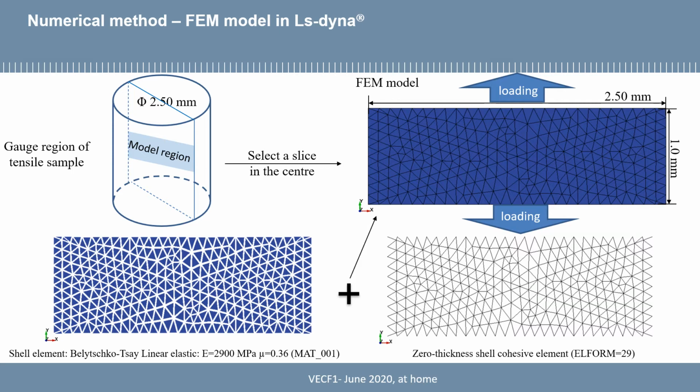With this, we only use linear elastic material models, and both the modulus and Poisson's ratio came from the manufacturer data. Besides, we use zero thickness cohesive elements, and because it's zero thickness and also a shell element, it's just like a beam. It's a beam-like element, and we use this to capture the behaviors of the RTM-6 epoxy resin and mimic the crack of this material.